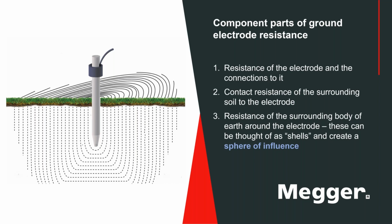Okay, so there's the resistance of the electrode itself. This can be discounted because that's a large metallic object. Now, the contact resistance between the electrode and the surrounding earth, you might think this would be a problem, but as a rule, it isn't. The fault current is able to transfer pretty well from the rod over to the surrounding soil.